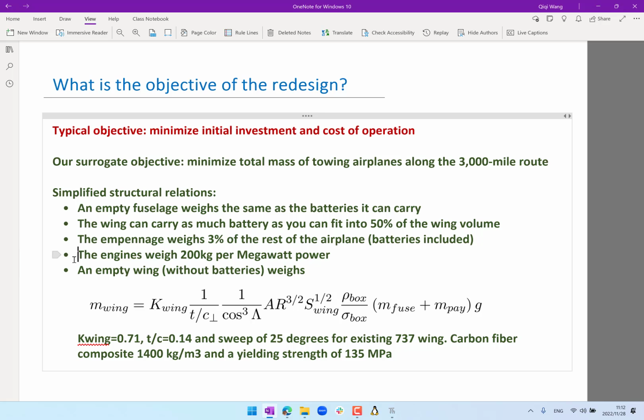An aerodynamic chord would follow the direction of the free stream to measure how much chord the wing has. This C orthogonal is the chord from a structural perspective. It is what you get if you cut orthogonal to the spar of the wing. That's basically taking into consideration the sweep. That matters for structural reasons and therefore matters for the weight.